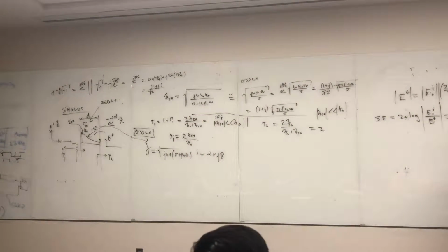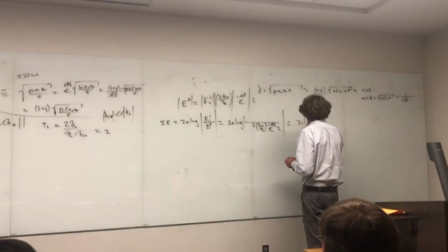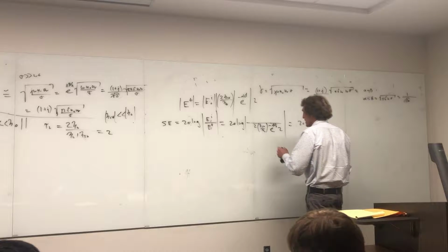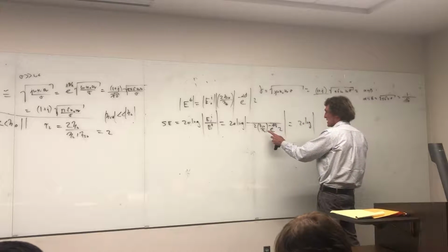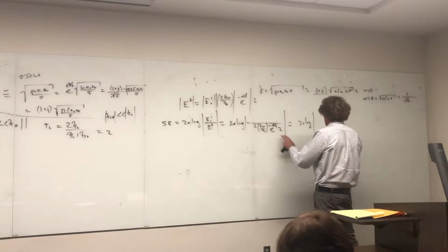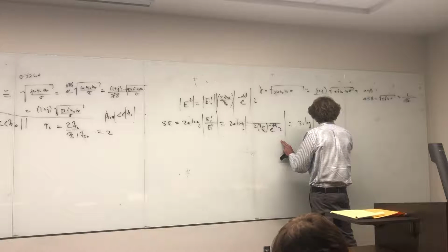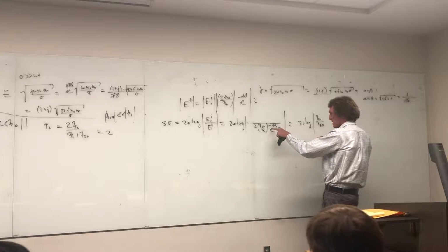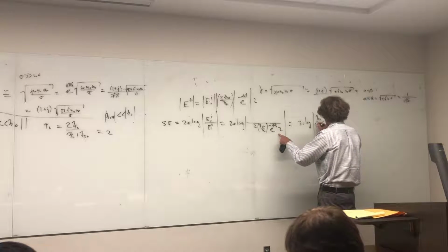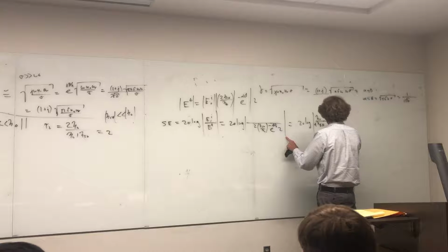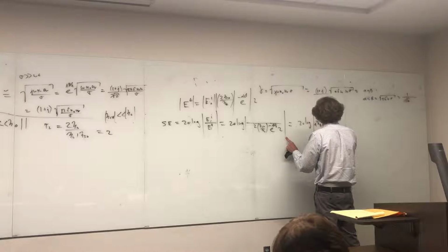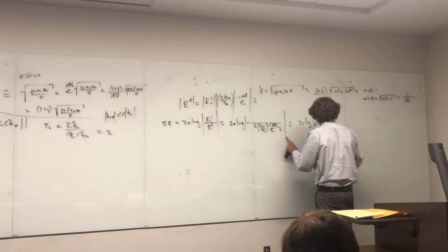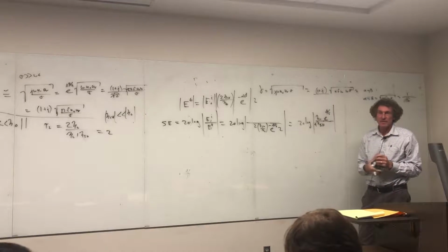And that's magnitude. Now, you can see here that this really breaks down to be simply 20 times the log of the magnitude. And take a look at this. I can get eta naught over eta shield, take 1 over this thing, right? It's divided by 4 because it's 2 times 2. And then it's times e to the d divided by the skin depth here. And that's the shielding effectiveness.